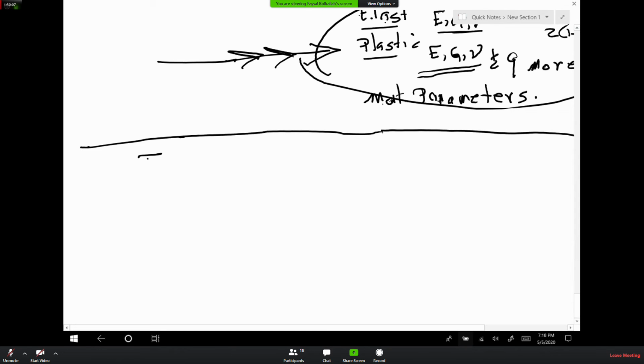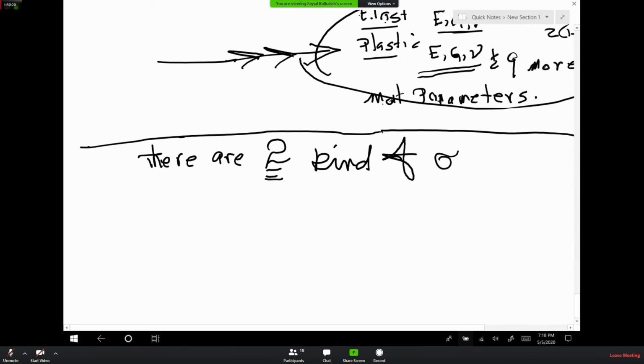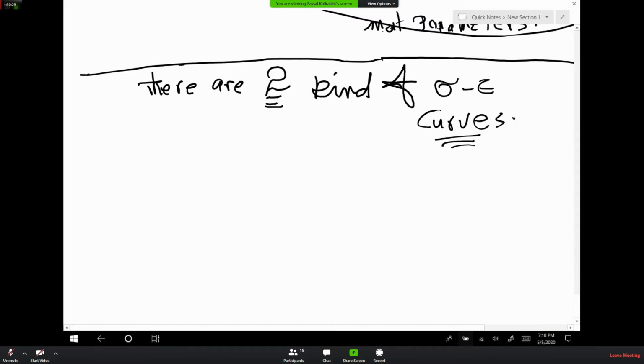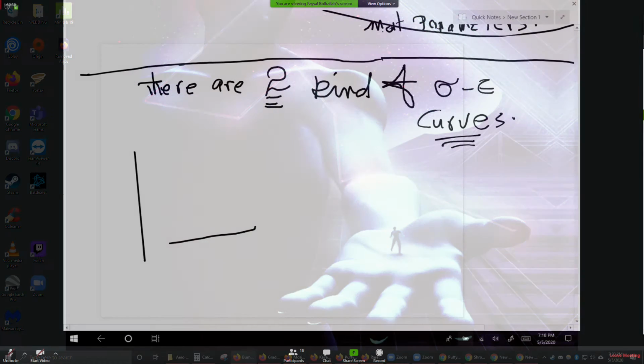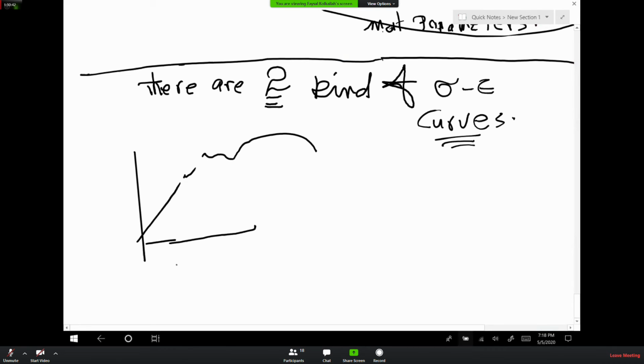There are two different kinds of, I'm going to call it just stress strain curves. I'm calling it stress strain just because I'm lazy, but you know, we mean strength and ductility and stiffness. One of them we just talked about, which is this. We call this monotonic loading. As I'm sure you did in the lab, you put the specimen and you pull it. One end is staying and the other end is pulling. That's how you get the stress strain curve as such. And we did that.